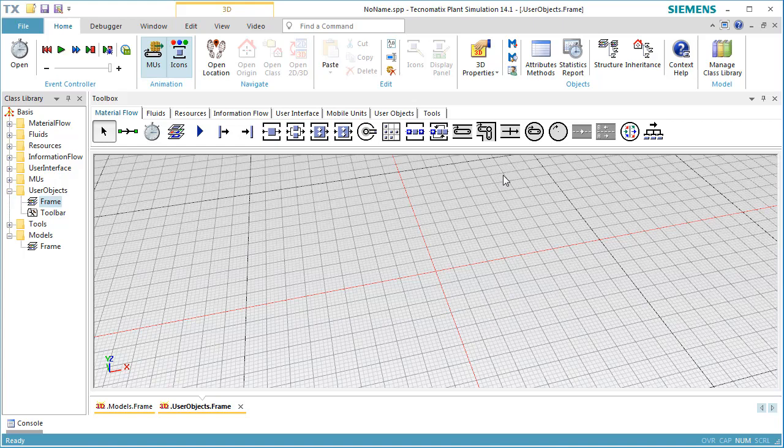In the first step, the drilling head has to move down fast and stop a short way above the product. In the second step, the drilling head has to rotate and move slowly down until the hole is drilled all the way. The time for drilling depends on the thickness of the moving object. In the third step, the drilling head moves up again slowly and continues to rotate. In the fourth and final step, the drilling head moves up fast to its default position.